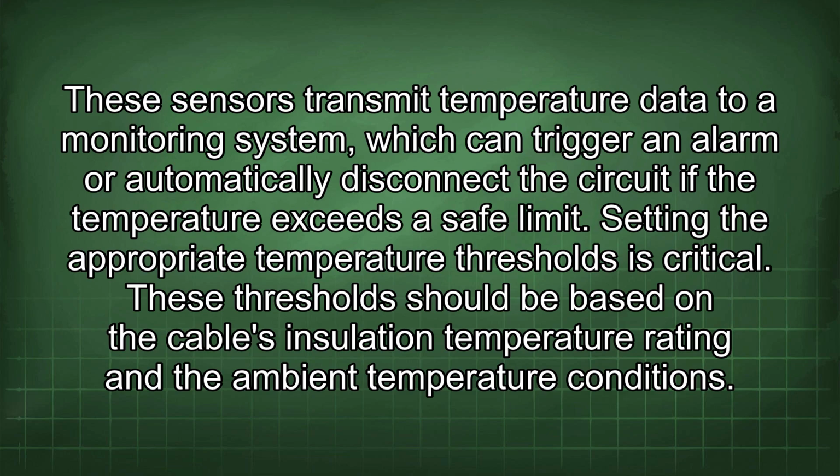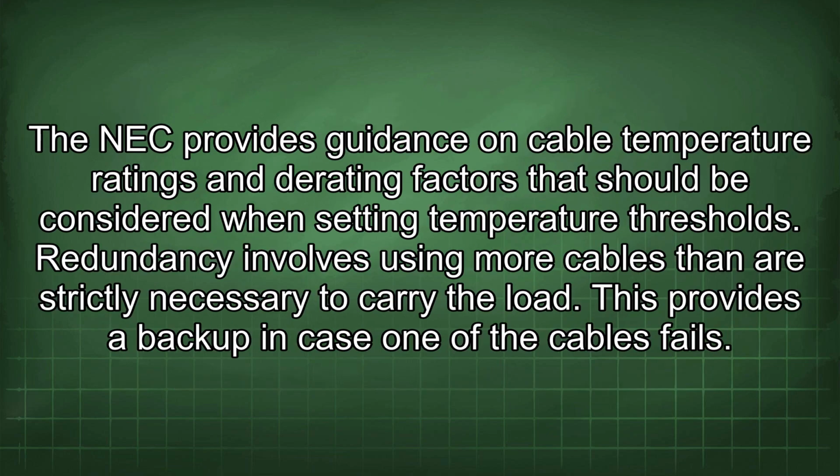Setting the appropriate temperature thresholds is critical. These thresholds should be based on the cable's insulation temperature rating and the ambient temperature conditions. The NEC provides guidance on cable temperature ratings and rating factors that should be considered when setting temperature thresholds.